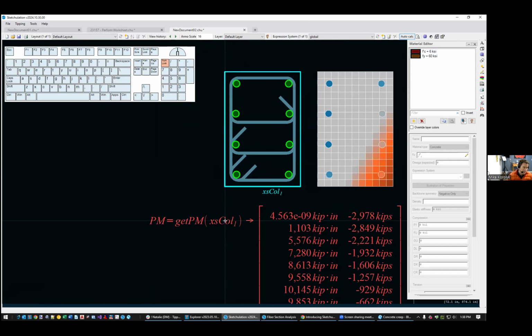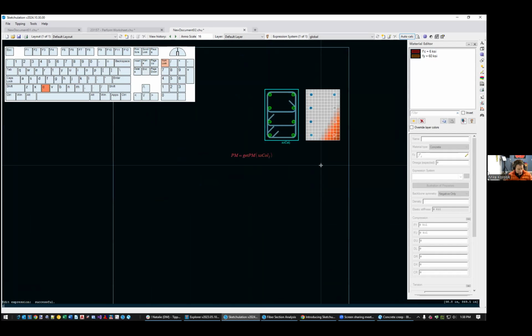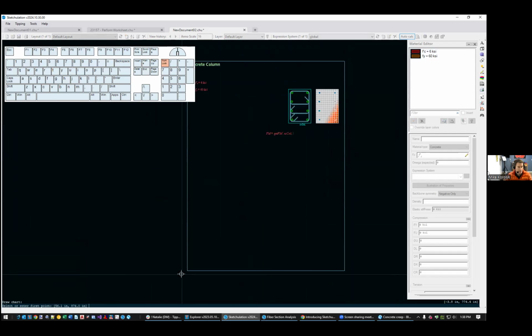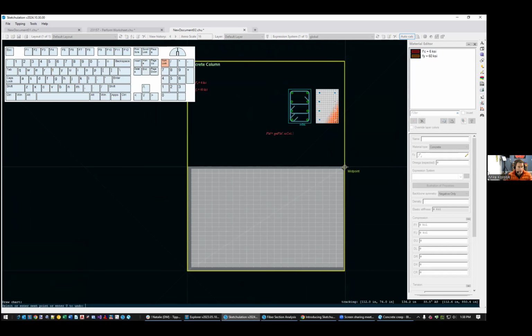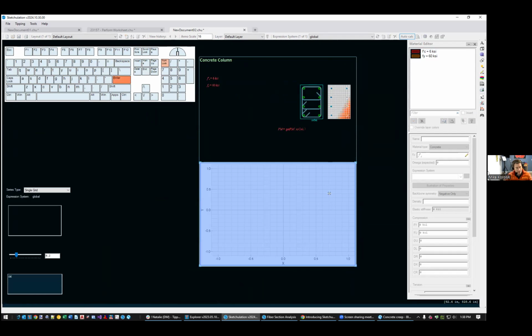Now, let's say that's useful, but I might want to graph that. So I can graph that in a chart. I'll make a chart, CHT, and I'll draw it off like this. Then I'll type SCR to make a series, and I go in here. I want an expression. Oh, no, I want vectors actually. This is two columns of data in an array, so that's usually with the vectors. I could do it with an expression.